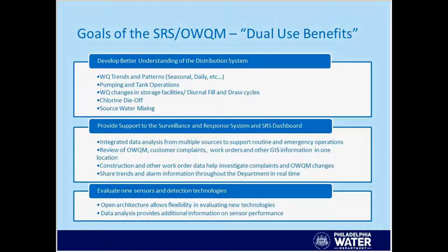So how do we use it? We use it to develop a better understanding of our distribution system. We're learning water quality trends. We're looking at how pumping rates and tank operations affect our chlorine die-off and potential nitrification in storage tanks. We're looking at how mixing in the lower parts of our distribution system are affecting water quality.